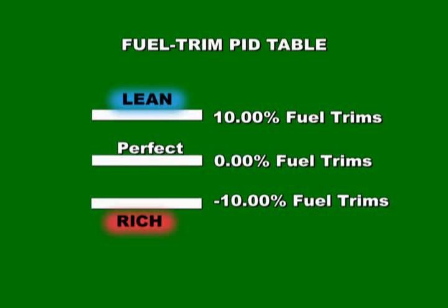Use the O2 sensor signal graph and the short-term fuel trims while moving a propane tool through the intake gaskets and hoses. Take all precautions due to a fire hazard. As soon as the vacuum leak is reached, you'll see a rise in O2 sensor voltage and a shift in fuel trims. It is estimated that up to 60% of all O2 sensors are replaced unnecessarily.